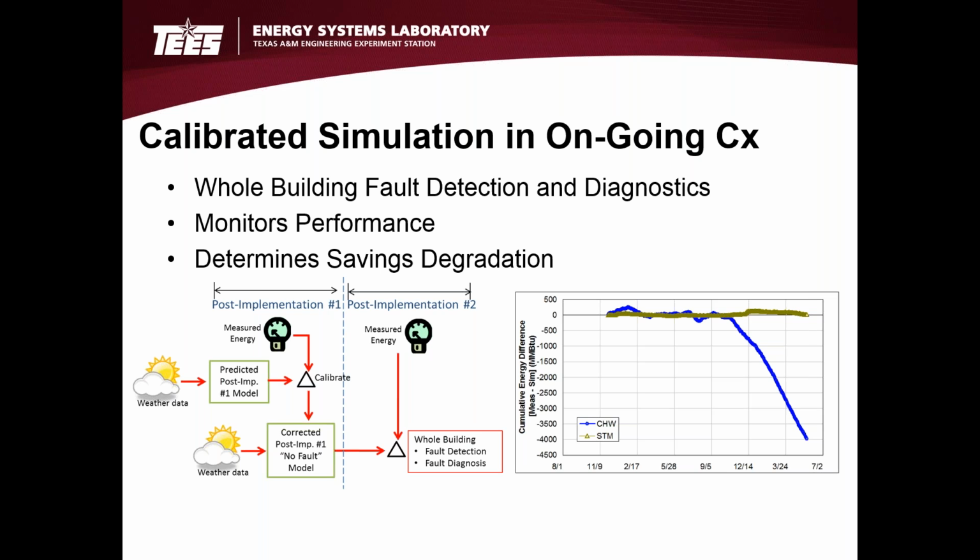illustrations of a change occurring that we have seen, but we have seen other changes too. Another example I can cite was one where we concluded that the outside air pre-cooling unit in a particular building must have had the temperature set down. When they went and checked, lo and behold, the temperature had been dropped from 55 degrees Fahrenheit, where it should have been, down to 45 degrees for pre-cooling.